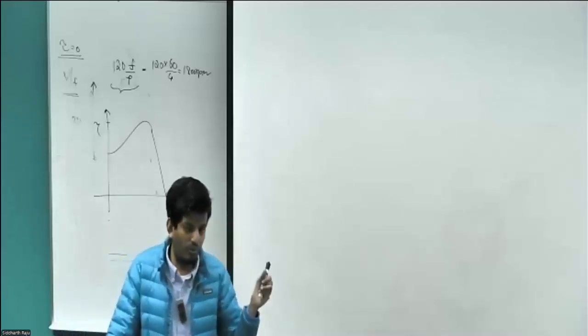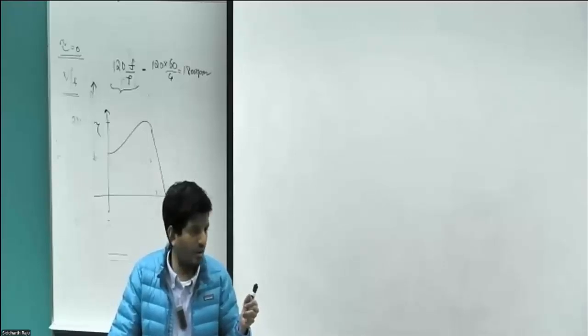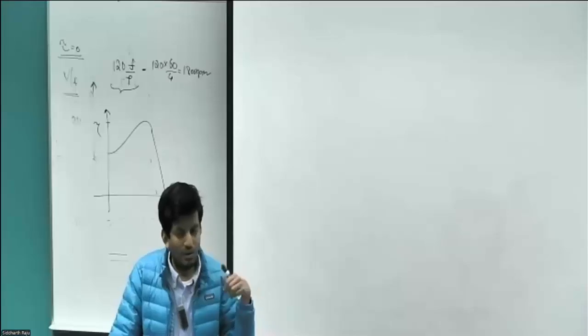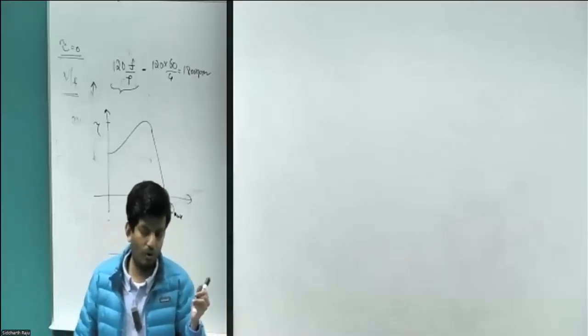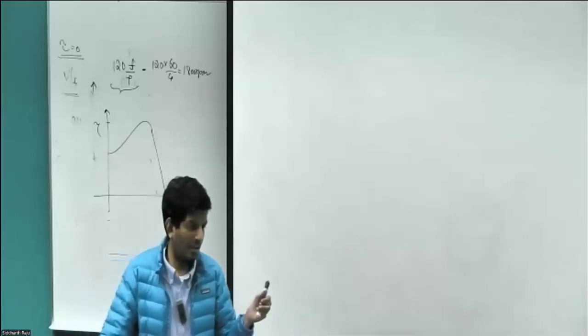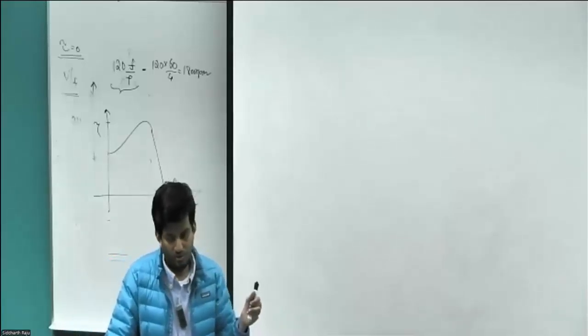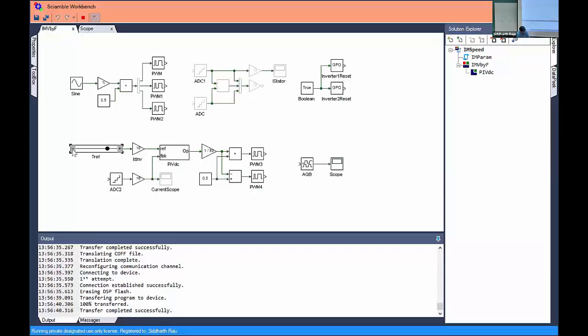What that effectively means in reality is you can take a 3-phase induction motor that's rated for, say, 220 volts, and directly connect it to a 220 volt 3-phase outlet in the wall, without having to gradually ramp up the speed of the motor or any such thing. So it is extremely robust in that sense, and that is what has made it the workhorse of industry. So let's go back to the model. Now the speed is 0. Let me start reducing the torque.